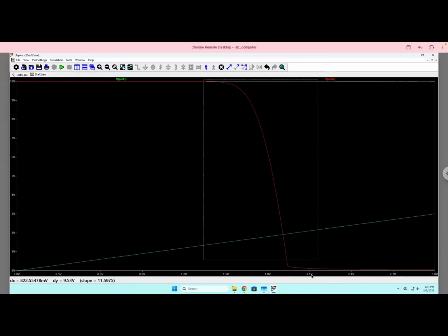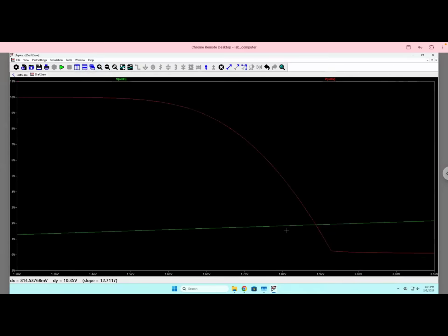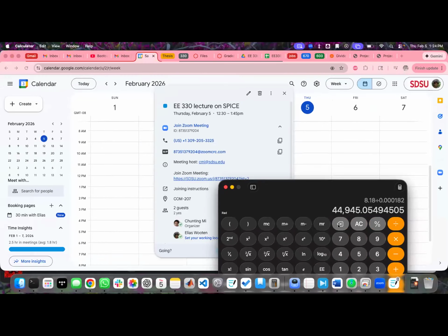Yeah, so you can do it with the modeling tool or you can resimulate it. Either one works. Cool. So 1.92, maybe 1.93 volts. And then you can see it's not truly linear, but let's call the bottom half 1.76 volts. So if we subtract 1.76 from 1.92, the delta is 0.16 volts. So we divide that by 2 and we get 0.08.